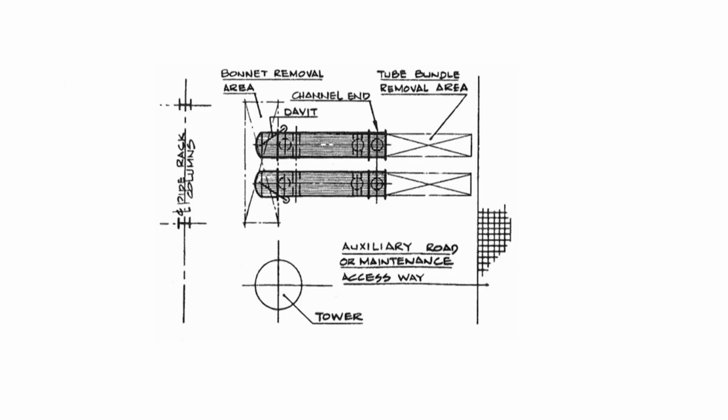So whenever you're doing a heat exchanger on the left, you see the area which is at the cross, that's the tube bundle removal area. So if you, for example, put a distillation column right next to the reboiler, you'll have no space left to pull out the bundles. This is the thought that goes. I'm not saying this is rocket science or very difficult calculations, but I'm just telling you, outside of the simulator, beyond that, when you see a good plant which is well laid out.